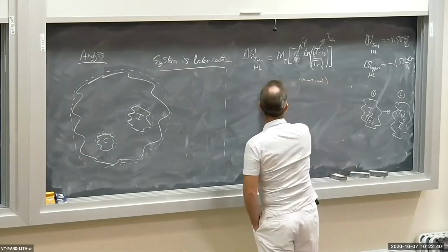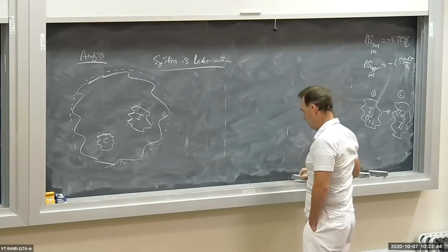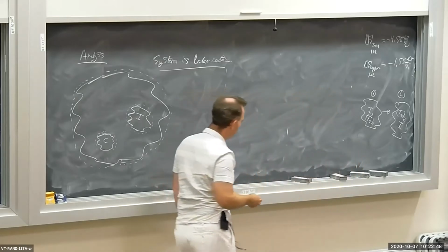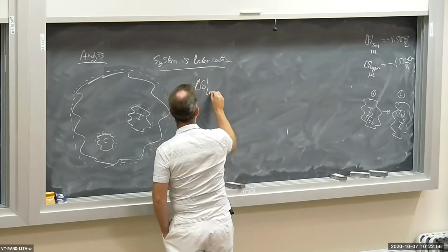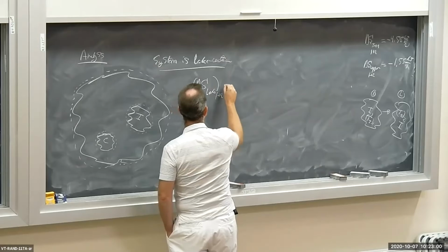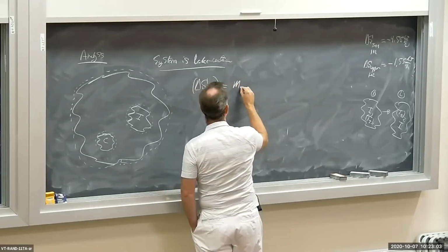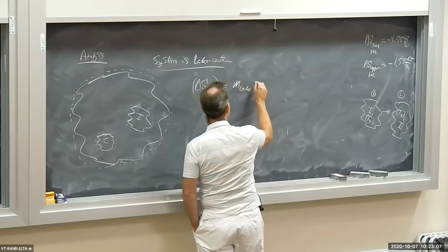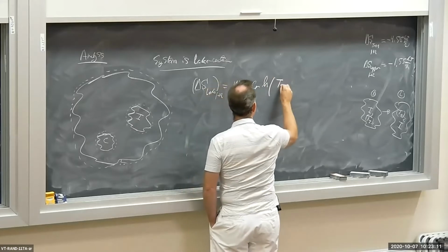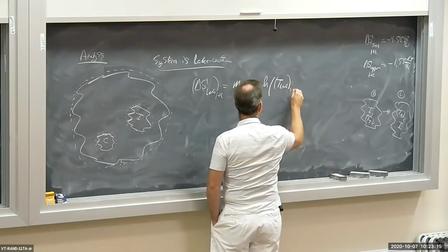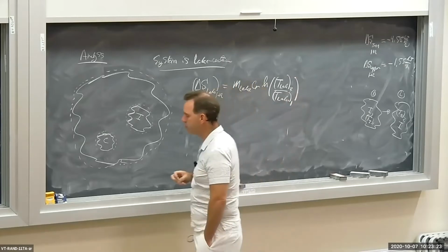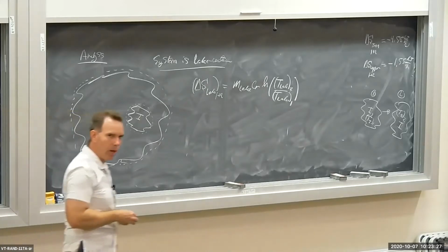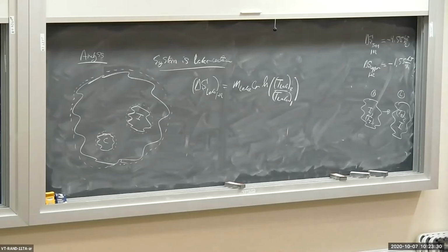Now let's see if I can calculate delta S for the lake using the property relationship that I used for the iron and copper. So delta S for the lake from state 1 to state 2 is M lake, Cv, ln of T lake 2 over T lake 1. So you might try writing this, and let's see if we can calculate the change in entropy of the lake. Well, we've got a bit of a problem here. I don't know how much water is in the lake.